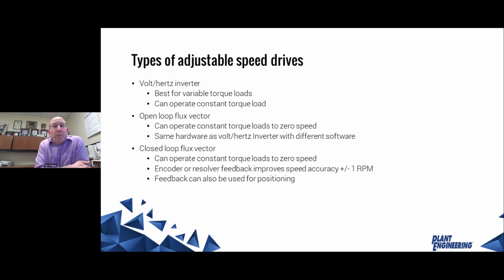There is something called open loop flux vector and closed loop flux vector drives. In many cases, those drives can be the same, and it just comes down to whether they're connected with a closed loop speed reference or not. A flux vector drive can do a variable torque load. It has the capability to run your fan or your pump. It just may have a lot more capabilities than that. So it may be a little more expensive, potentially, and it might take a little more to set up because it has more capability, so there is a little more that has to be set up.